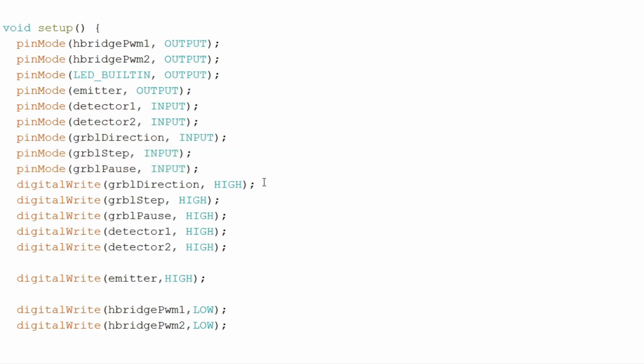Next, we call the digital write function. This function, when used on a pin set to output, sets the state of the pin. When used on a pin configured as input, it can activate the built-in pull-up resistor. A pull-up resistor is used to pull the logic level of the pin high so the external circuit can cleanly pull it low. This is the standard practice with most digital circuits, as pulling low is less susceptible to noise than an external circuit pulling a pin high when tripped.